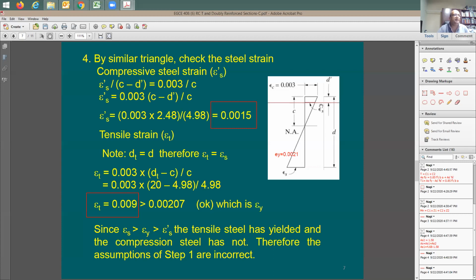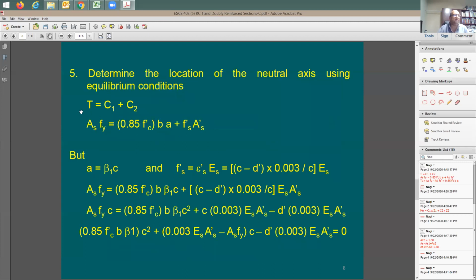Okay, good. So the simplification started with, I cannot really do it. So what I need to do is to start with this equation here, right? Knowing that the tension steel is going to be all yielding. So this part of the equation is correct. This here is something that I learned based on this analysis. Otherwise, I would have just said AS times FS, right? It means that both of these two steels are not yielding yet. But now I confirm that the tensile steel is yielding, compression steel is not yielding. So I was able to refine my equation to this format.